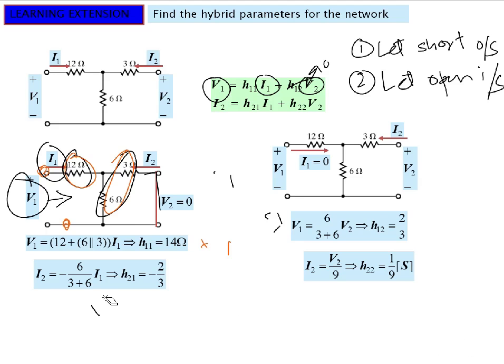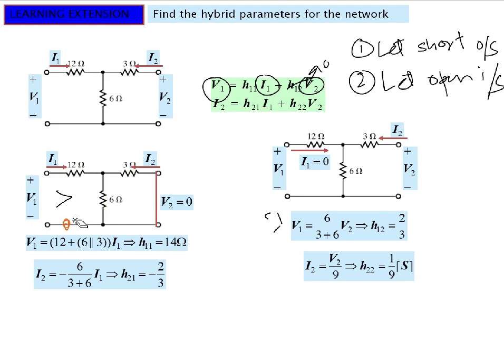So now coming towards this H21, why are we calculating H21? Yes, you people are talking about it right now in a correct manner, that since we have already short-circuited the second port, by short-circuiting the second port we can find H21 easily.